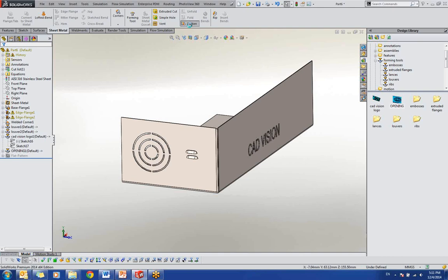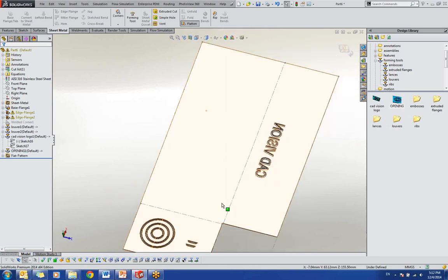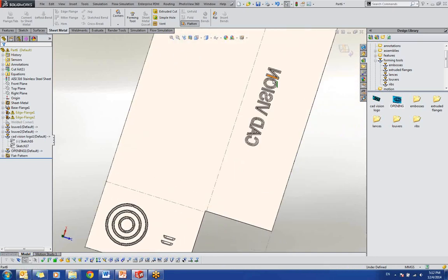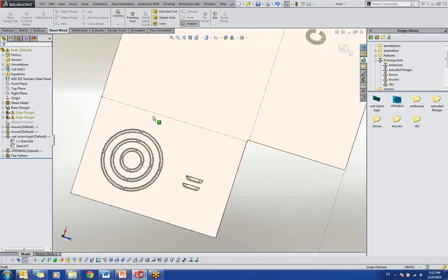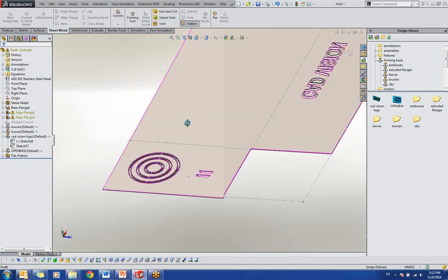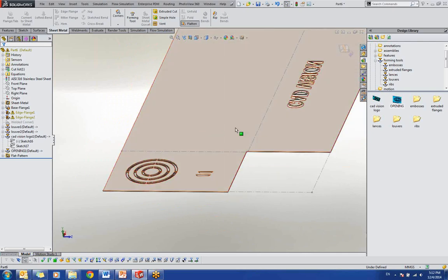When I flatten it, it takes some time. Okay, you see here, if I flatten it, it will show that the form is already formed here. All the forms come out, and then it's just the bend and the welding. Actually, all the forming is done before the bending process. The punching process is done before the bending process. So this is the logic schema.